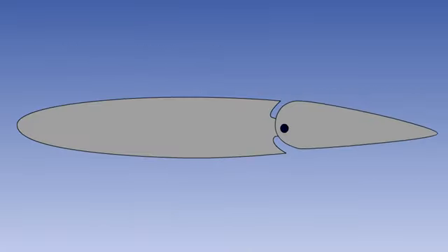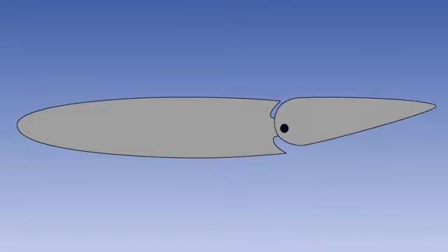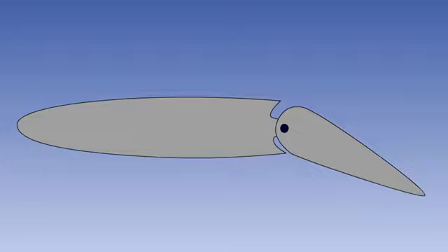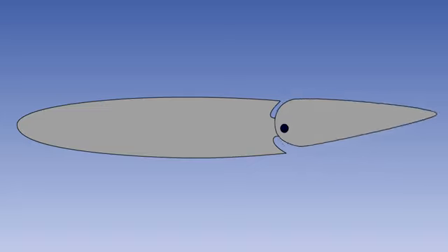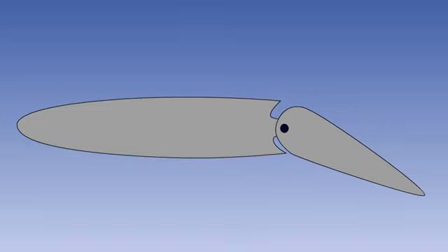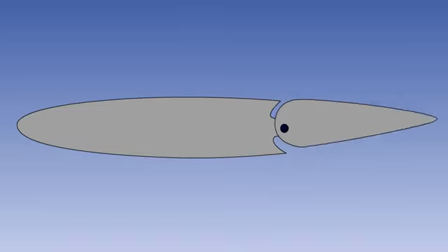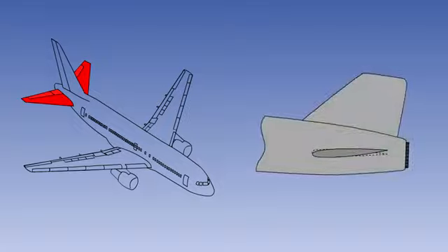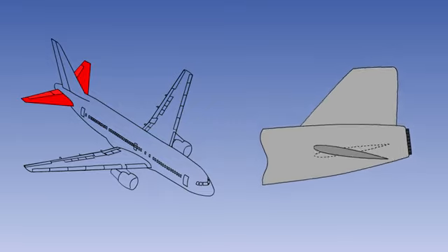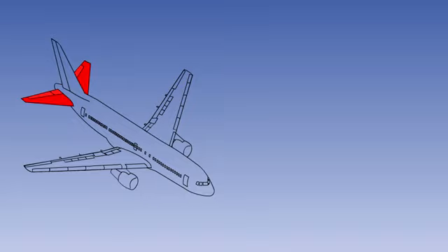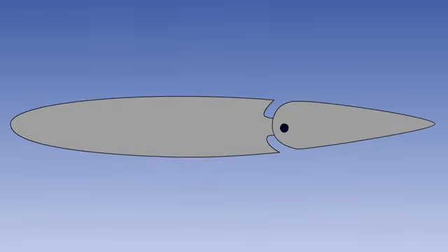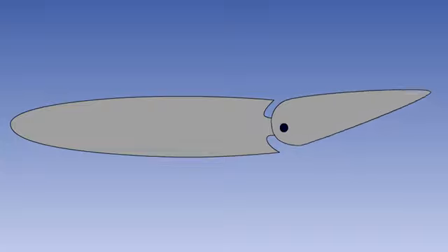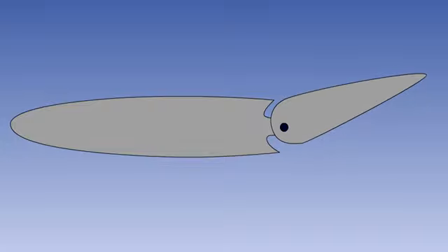The movement around an axis is produced by changing the aerodynamic force on the appropriate aerofoil, wing, tail or fin, and this may be done by changing the camber of the aerofoil by deflecting a control surface, changing the angle of attack or incidence of the aerofoil, or decreasing the aerodynamic force by spoiling the airflow. The most common method used is to change the camber of the aerofoil.